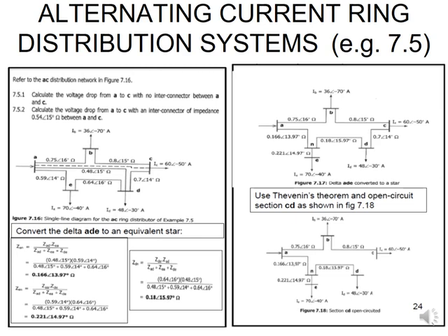With this, they then use Thevenin's theorem and open circuiting. They've chosen the circuit C and D to open circuit. And you can do this because unlike the previous one where you only had the 3 different nodes, it made better sense to go to the opposite side to do your open circuit after you've done your delta to star conversion.